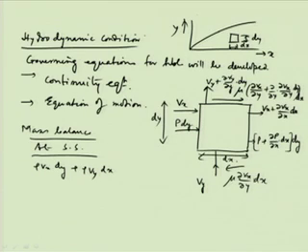So, dy into 1 will be the area through which the velocity Vx is moving. So, dy into 1 gives the volumetric flow rate. Volumetric flow rate means meter cube per second, a volume flow per time, and rho is the density, so rho becomes the mass flow rate. So, this is the mass flow rate actually.